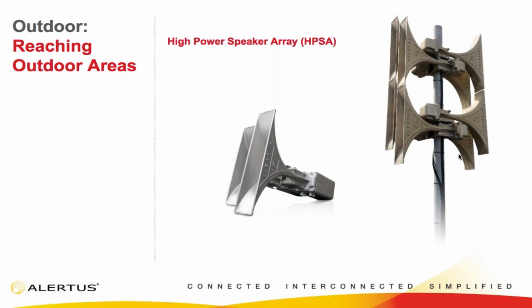I am going to get into a little bit about our acoustical designs and how we determine where to put these. On the far left, this one we're going to talk about briefly. That's our 100 watt speaker. That's just a self-contained 100 watt speaker. These are for acoustical shadow zones, areas where the sound doesn't go, but we still want to cover, right? But we don't want to put in a whole high power speaker array. Maybe it's a playground or a quad area, or a sports field where you just want something small and simple. We can put that in there. But what wattage we use and where they go is going to be a result of that acoustical design.